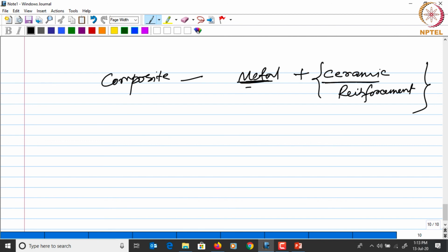So here the sintering approach remains the same, but the densification process could be different due to the presence of these kind of insoluble particles. So here you mostly have to look at how these insoluble particles bond to the metal during the sintering process, right? So although the basic mechanism is going to remain the same, the interface between this ceramic and the metal is going to play a dominant role in this case, because here we have to see how this interface is created and how the bonding at that particular interface is occurring during the sintering process, okay?